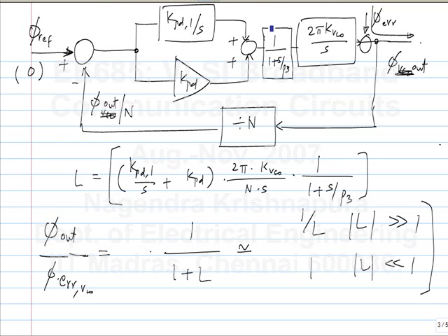Now finally, if I add an error here, what do I get? How will I evaluate that? Oh, that part divided by 1 plus loop gain. Yeah, that's correct. So what does it look like? Again you can write the classic feedback block diagram with this part being the forward path gain G and the loop gain being GH. Okay. So what does it look like?